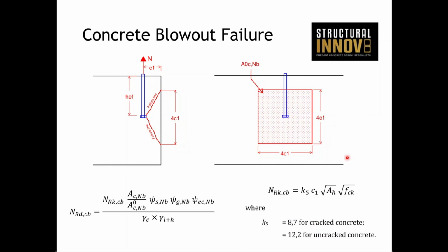Now, blowout. I haven't spoken about blowout yet, but because we're in a relatively thin wall panel, we're only 150 millimeters towards the edge. So what can actually happen is that you get a blowout emanating from the foot of the lifter. Now, it is a socket we're using here. It's a wavy tail socket, so the distribution will be a bit more favorable. But again, just to stay on the safe side, we assume that all the pressure goes through a single point, like would be the case with a spherical head.